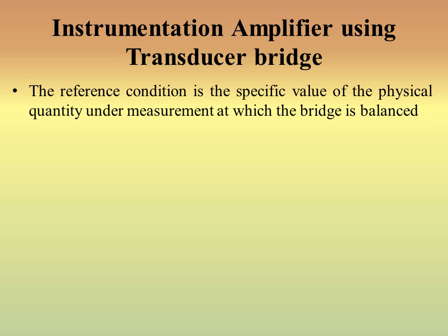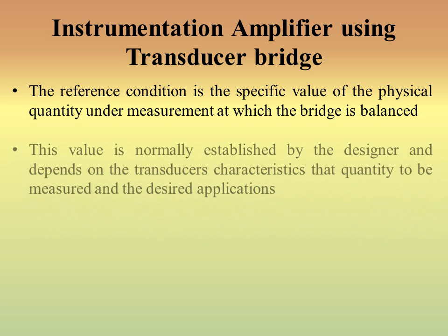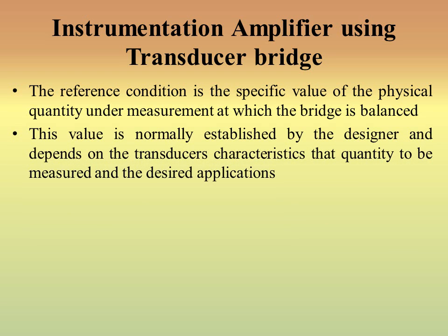For the reference condition, the resistances are so chosen that the bridge remains balanced. This value is normally established by the designer and depends on the transducer characteristics, the quantity to be measured, and the desired application.